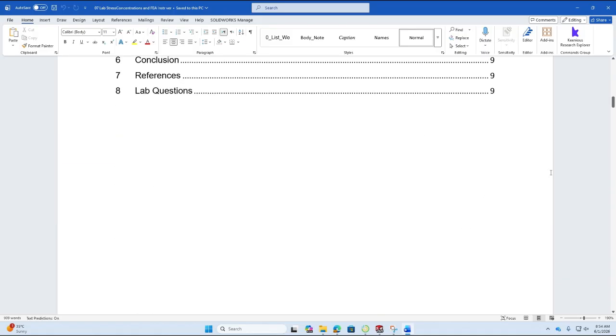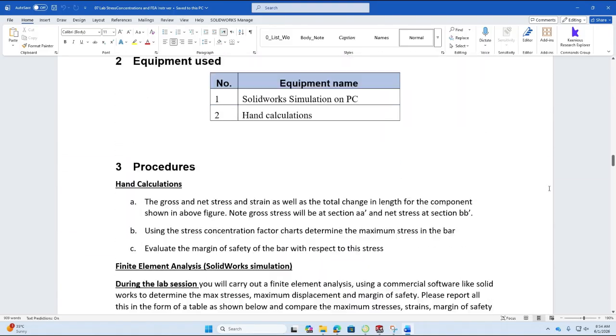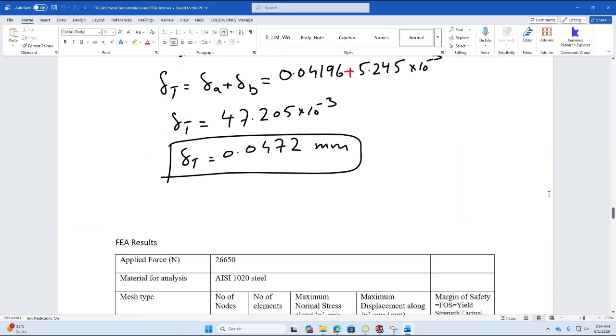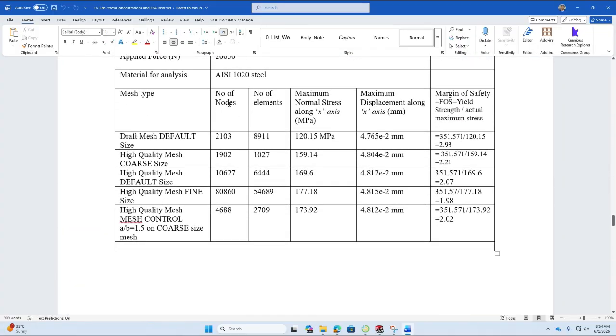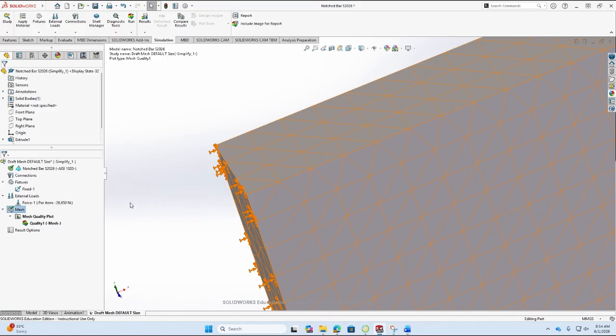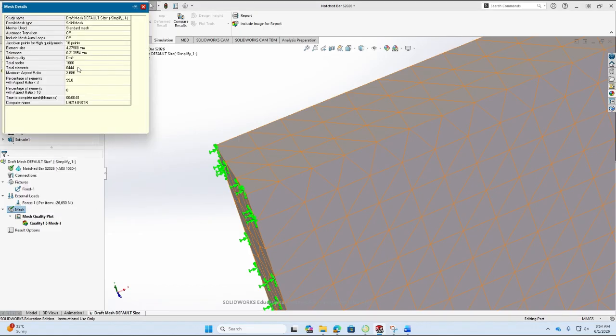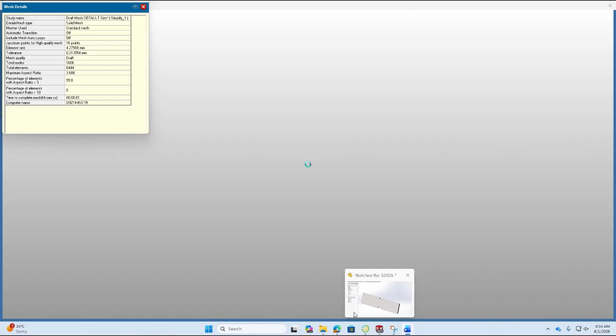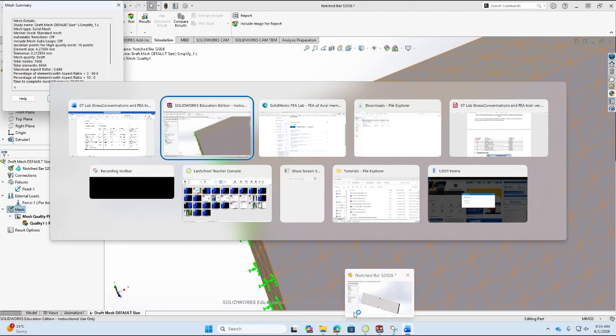So I am noting down this data in this table. On the top you've got number of nodes and then you've got number of elements. Last time when I ran this analysis, maybe the settings were slightly different, therefore I got slightly different numbers of nodes and elements. I can update this now. So how much is it today? It is 1606 nodes.